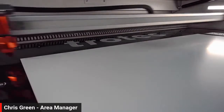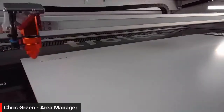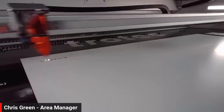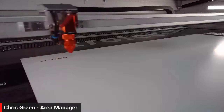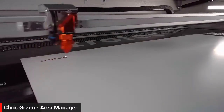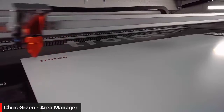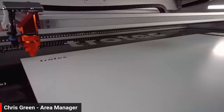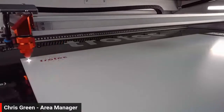So while the machine's starting up the extraction, you can see it's obviously coming across to the engraving. So typically we always engrave first, because when we cut, the part can move a little bit, and that can result in obviously some misalignment if the part moves at all. In this case though, it probably wouldn't be an issue anyway, just because Chris has got the bed all properly set up for the extraction system. So everything that isn't being used is all blocked off. That means that all of the extraction is going to focus around the cut line, pull the fume away really quickly, and that means that again there'll be less debris and less cleaning on the actual part itself.